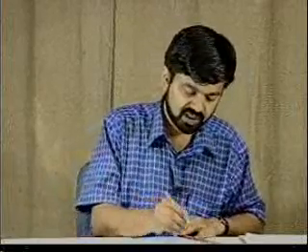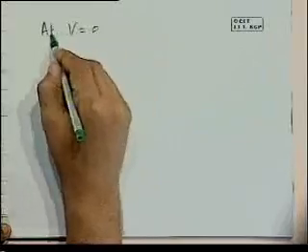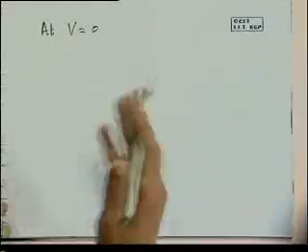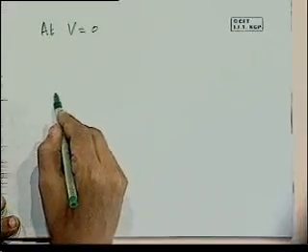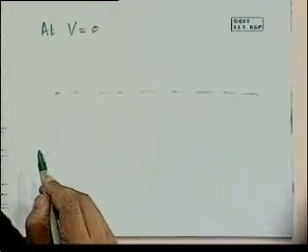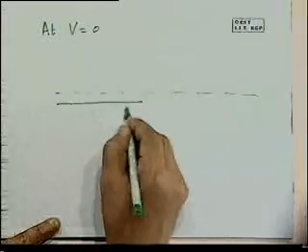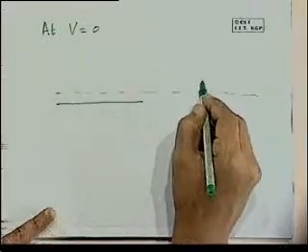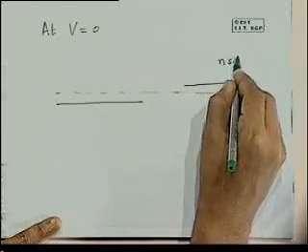What we can do is to express the whole idea that we have so far got in terms of the band picture. I'll draw three simple band diagrams. At V equal to 0, the zero bias, I really didn't draw that as we did for Schottky. We've got no bias conditions. First of all, the simple thing we know is that the Fermi level is the same on both sides in equilibrium. And so we can plot it: on the P side, it's close to the acceptor, to the valence band. On the N side, it is close to the conduction band.